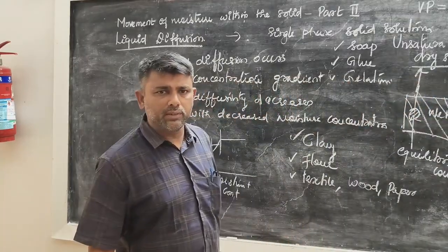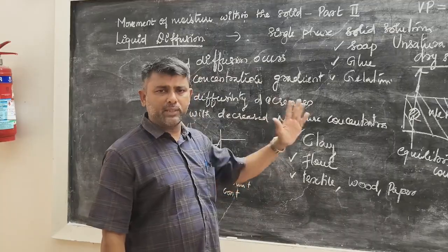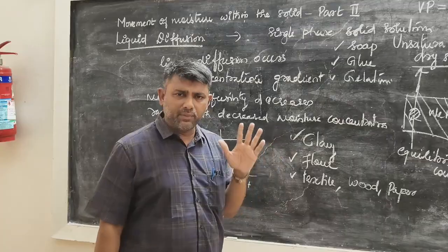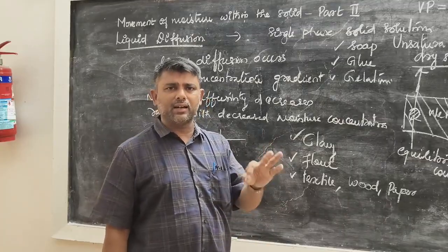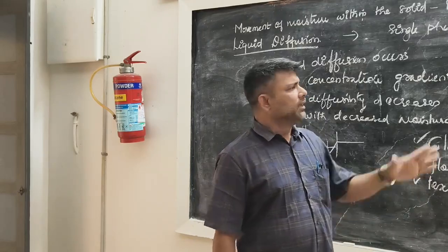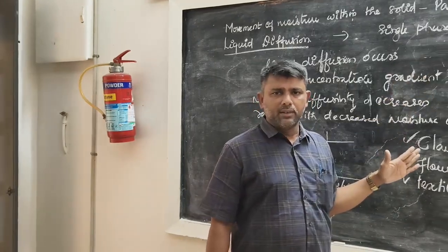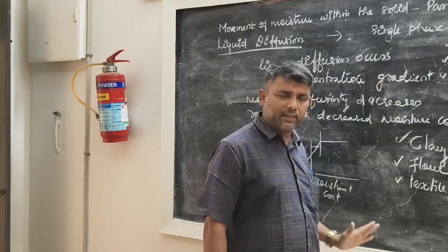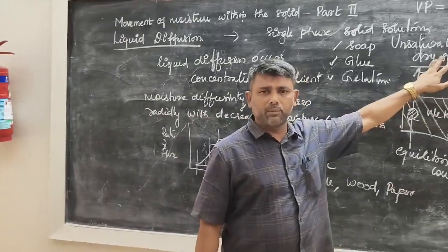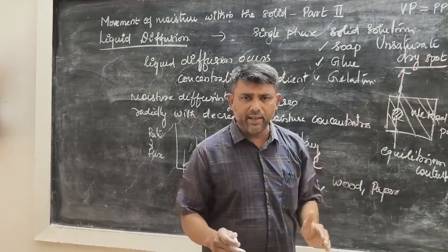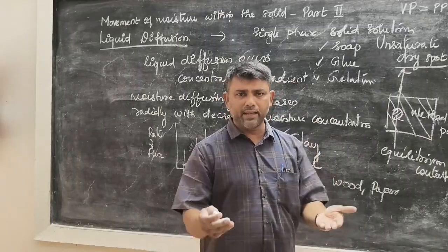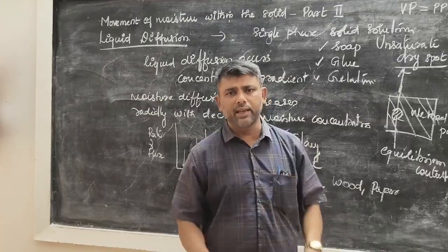In liquid diffusion, there will be a formation of dry spots at the end of the constant rate period. Appearance of a dry spot is the indication that the constant rate period comes to an end. Clear? At the end of the constant rate period, the falling rate period begins. A dry spot is the area projected directly into the gas film.